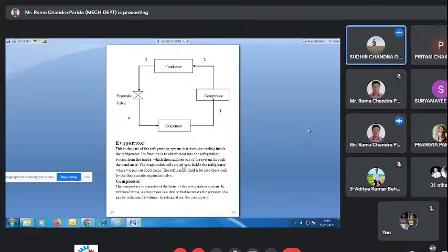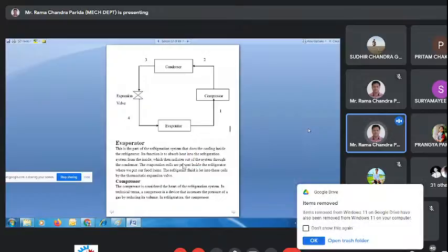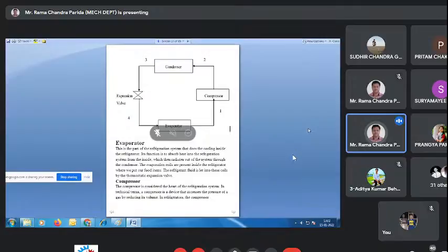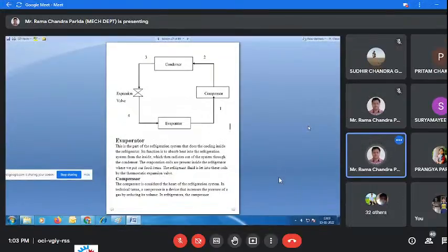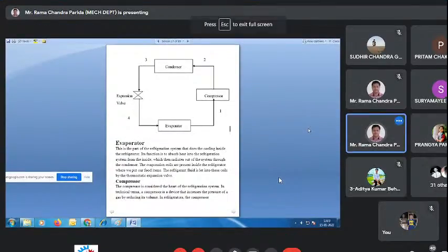So what I am telling is like the steam power plant, where we asked what was the condition of steam. Similarly, here I am explaining the condition of the refrigerant. The fluid which is circulated through the refrigeration system is called the refrigerant. We will discuss the refrigerants later. After the evaporator, the low pressure, low temperature vapor goes towards the compressor and there it is compressed. When vapor is compressed, its temperature also increases.